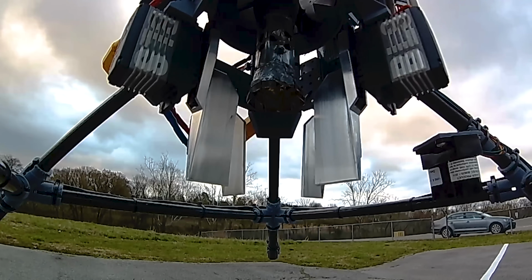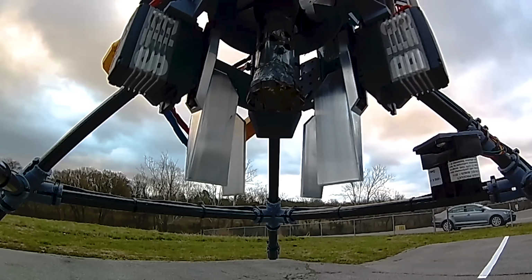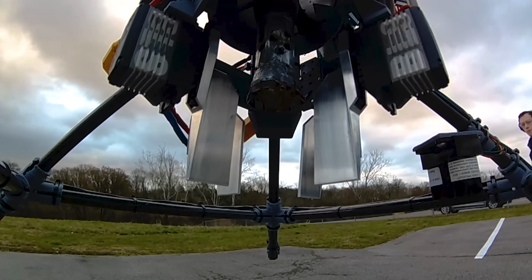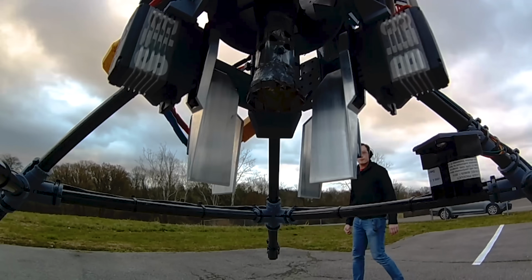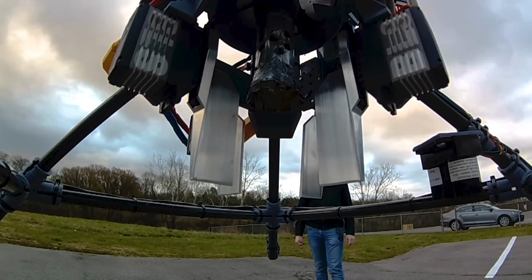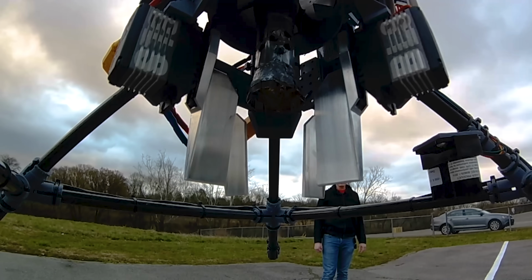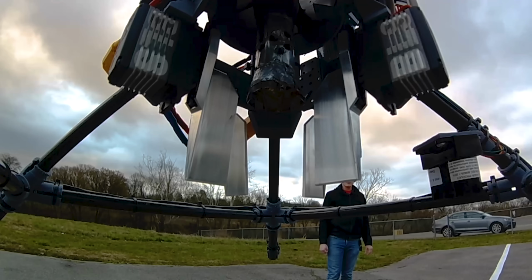So adding those stators in there allows those thrust vector control vanes, you can see it in this whole video, to be nearly straight up and down, which gives us tons of control authority during flight, much more than we would have if we were resisting the roll only with those thrust vector control vanes and not the stators, which exist above. Okay, and that's about it for the updates.